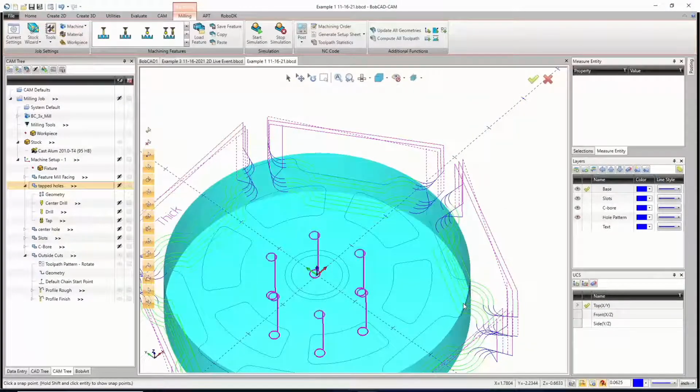And a lot of it comes from the fact that we're using wireframe geometry to define our holes. If we had a solid model and we picked the inner surfaces of the solid model holes, then when we say reselect geometry, it reads the diameter and the depth from that. So the odds of it not making a mistake doing it that way are better. But you'll always have to double check the holes, especially when the origin changes Z positions, because it can act kind of weird. So there we go.